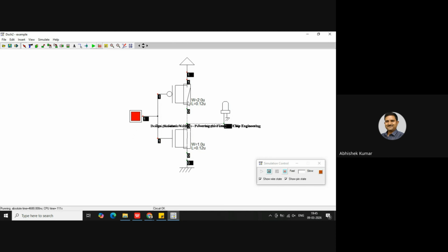So now here is the open connection. Current cannot go upward in the open path. Current will go into the downward closed path. So here the output is pulled down. So what is the message here? This NMOS provides a path for the pull down network to the ground.